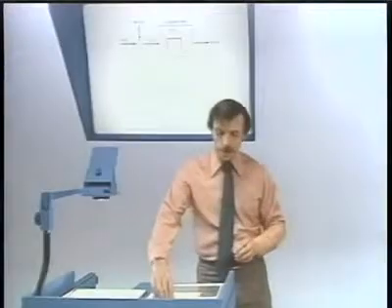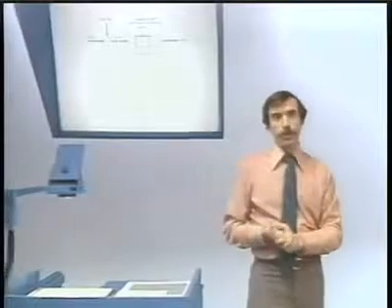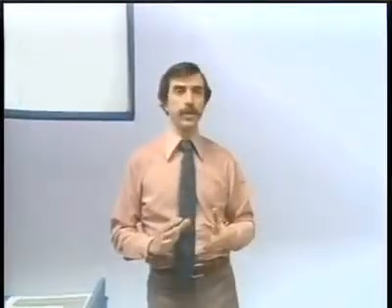Now, several other things to stress. This is a fairly quick tour through sinusoidal modulation for discrete time. There are very similar issues that arise in the discrete time case in terms of having phase synchronization and frequency synchronization between the modulator and demodulator. And we had discussed that in a fair amount of detail for the continuous time case.